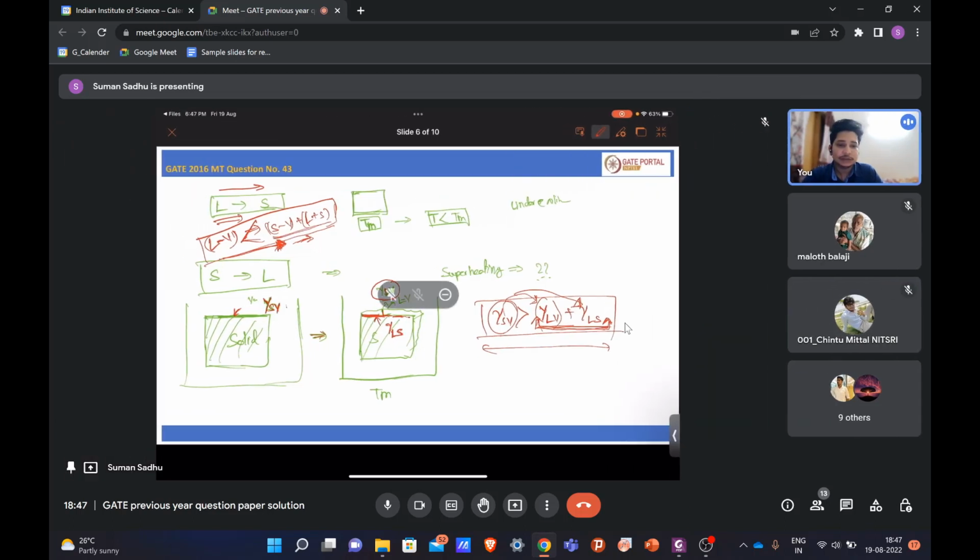Is that basically calculated experimentally? Just from seeing these things, you don't know that that energy will be higher. But experimentally it is found that the surface energy between these two is higher than the liquid-vapor and solid-liquid. So that's why every time you melt, you will find that it melts at the melting temperature itself.